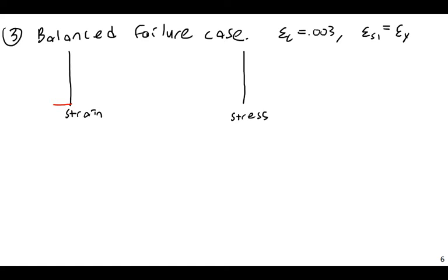Instead, what the code says is that structural engineers should consider interaction, so you're required to consider it, but it's not going to tell you how, just like it's not going to tell you how to calculate the moment of inertia of something, except for the more complex cases like effective moment of inertia. But unfortunately, this is not spelled out directly in the code.